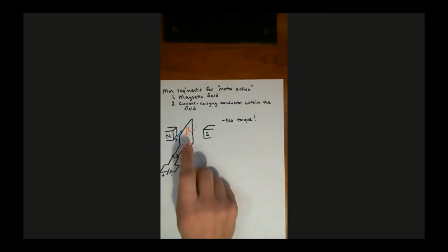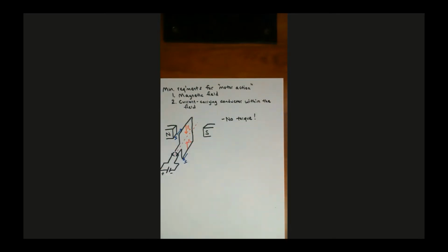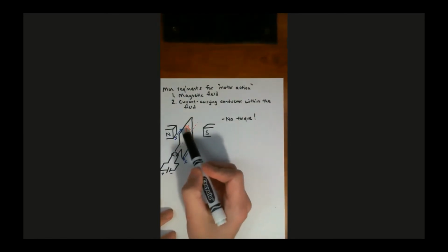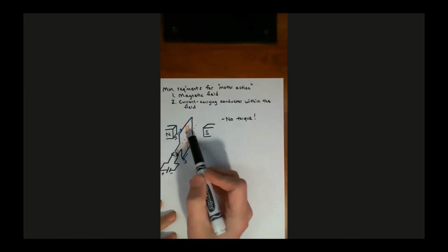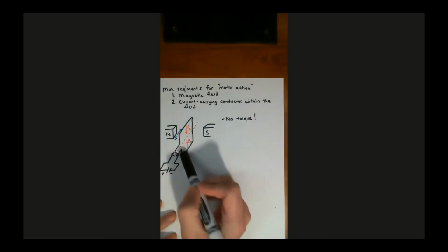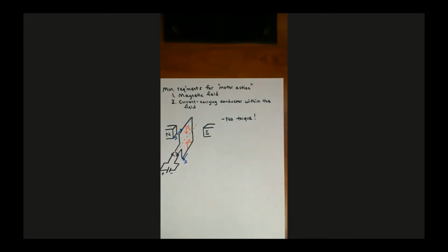If you had a really crude DC motor like this, then basically momentum is carrying it through this position up here. So once it gets away from vertical, then it will produce a torque again. But anytime the armature is vertical, it's not producing a torque. So first of all, I wanted to say that that's the reason why I'm allowing you to get it started manually for your extra credit DC motors. And the second thing is we want to avoid this situation, of course, in a real DC motor. So we don't do this design in a real DC motor.